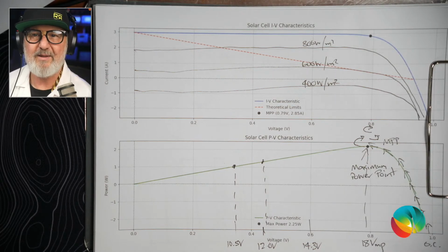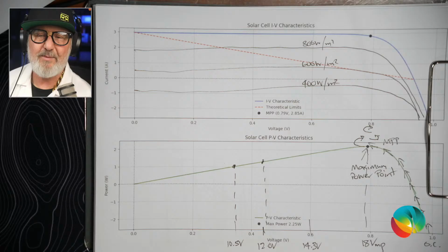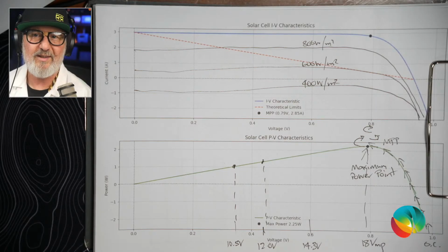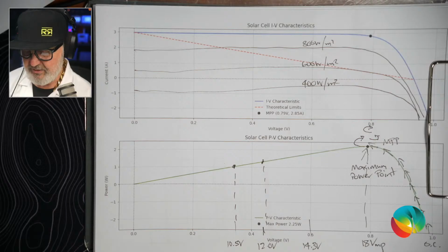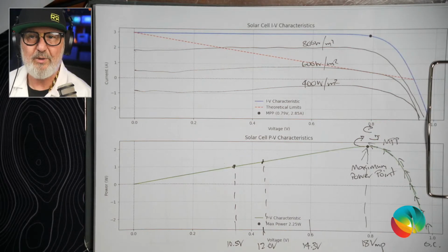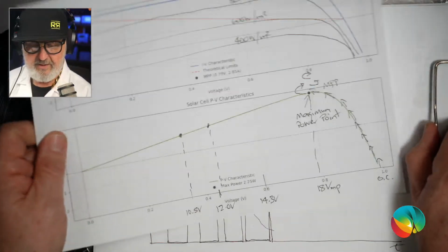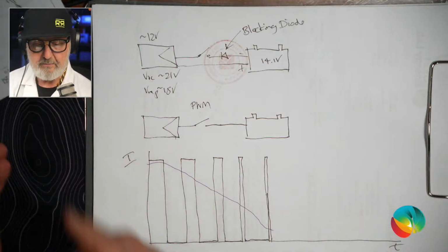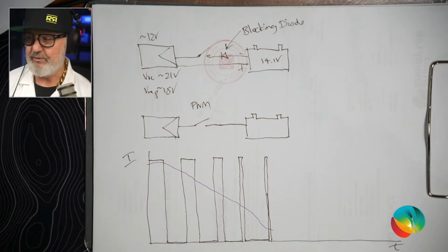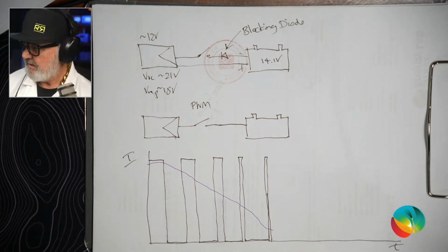You just want to keep the battery charged up when you're not using the vehicle. And so for a relatively modest $10 to $20, you can probably get a PWM charge controller. So they still have a role for those small applications. So there you go. The history of charging from when we used to do it with a switch, with a blocking diode, and we moved on to PWM and more recently to maximum power point tracking charge controllers.